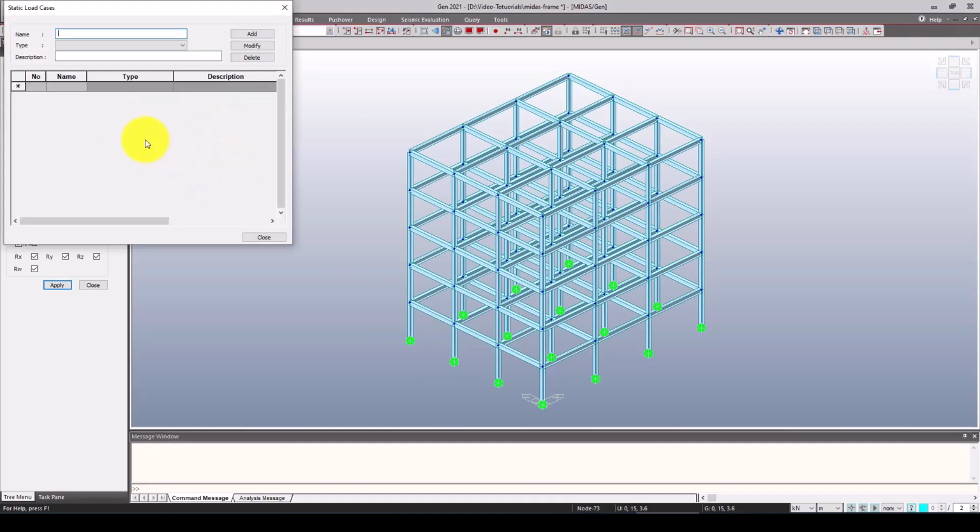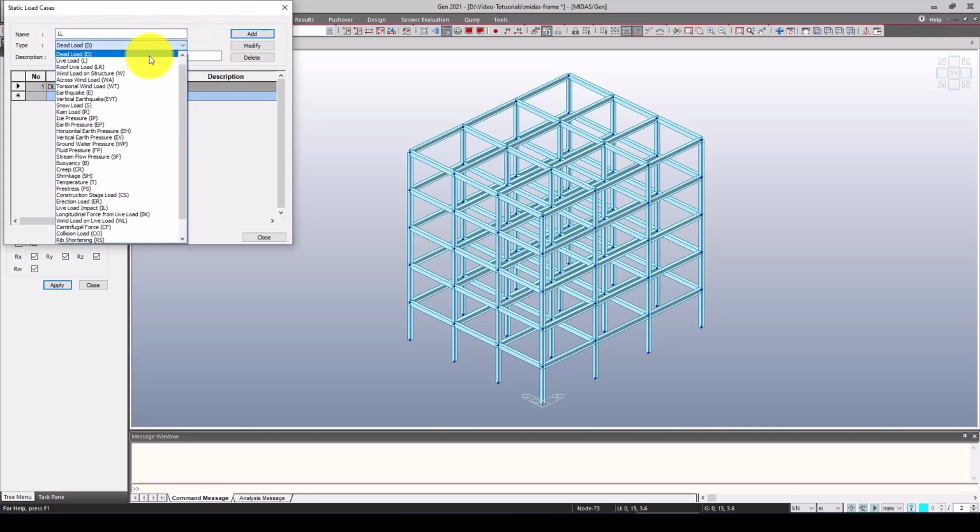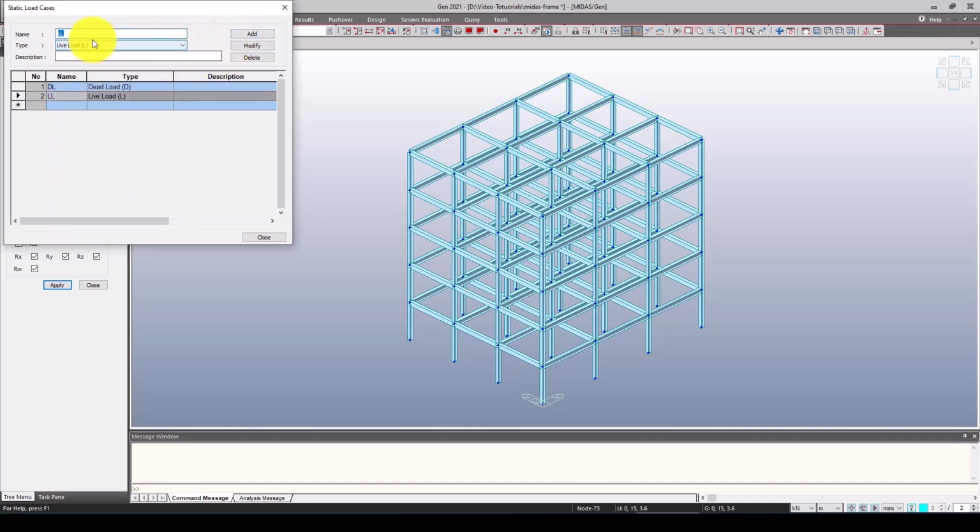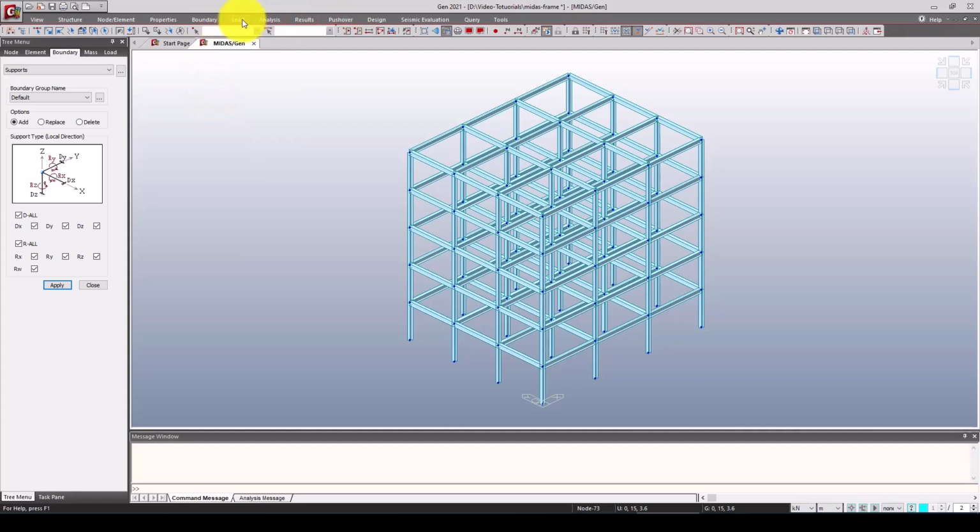So next I want to define loads. We have a dead load, which includes the self load, and live load, which is the floor load, and also the seismic load. I can consider two directions, because one direction is more stiff and one direction is less, x, and also adding y. Now first, go to the load.